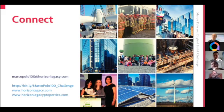As far as placement of machinery in the building, we would like to avoid a basement here. It's really up to you where you want to put the machinery. In Ontario, typically we see mechanical rooms being built on roofs. These mechanical rooms house central ventilation equipment that's used, for example, for pressurization of corridors or staircases or elevator shafts as may be required by code.